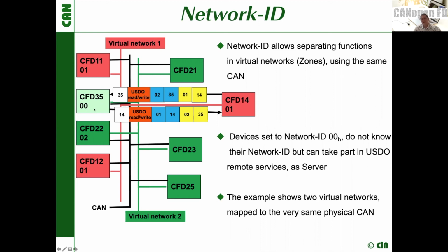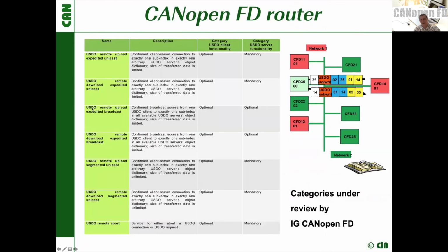It is a must, an obligation, for all CANopen FD devices to be capable, at least in this setup as depicted here, of managing remote accesses. Although it puts a certain requirement on the processing power provided by such a device for the treatment of remote accesses. Therefore, we have at the moment a discussion in the IG CANopen FD on how to handle remote accesses and which is the minimum requirement for CANopen FD devices with regard to USDO remote accesses.